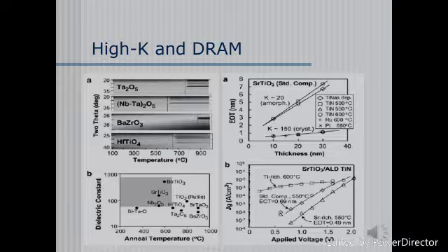The crystallization temperature is raised as the composition changes from the stoichiometric structure of SrTiO3, but the temperature still stays below 600 degrees Celsius. Electrically, SrTiO3 films change greatly, as the deposited films and films with a 500 degrees Celsius anneal end up with a dielectric constant of around 20.